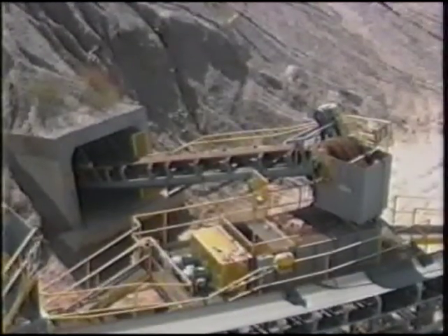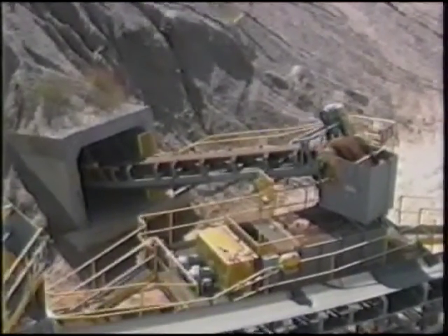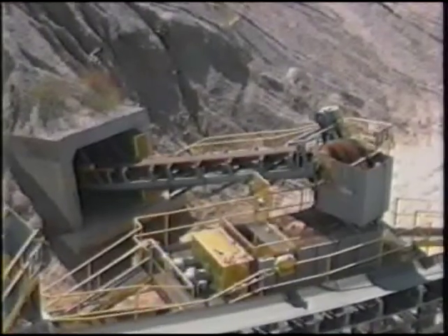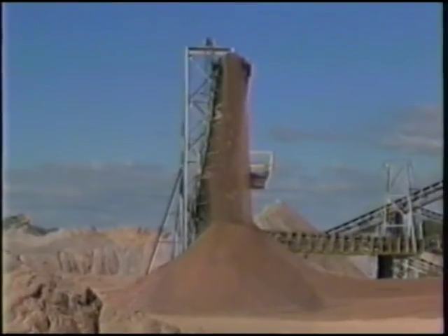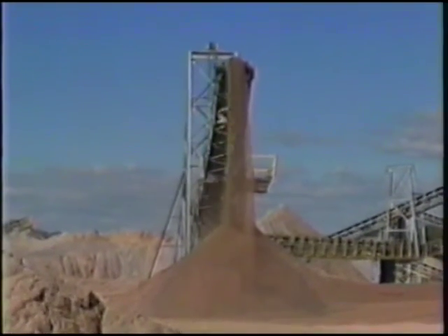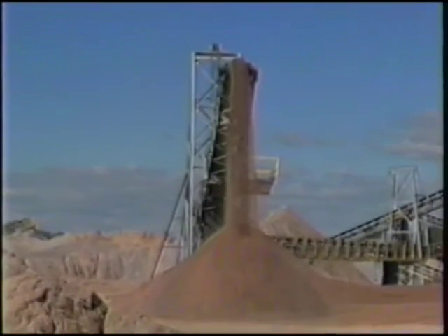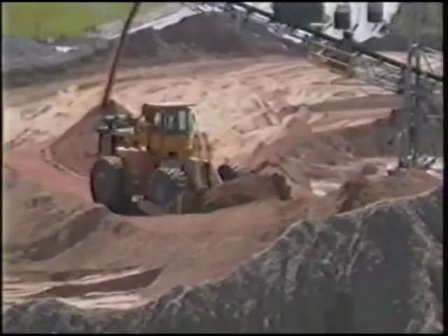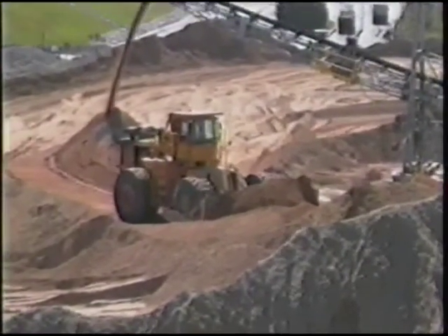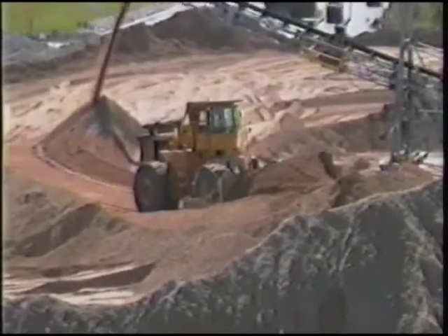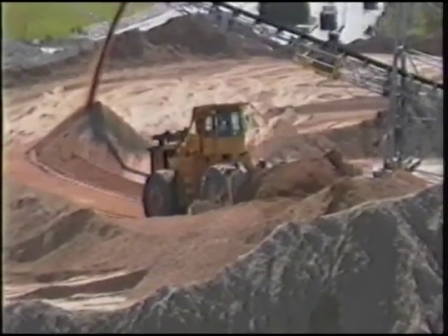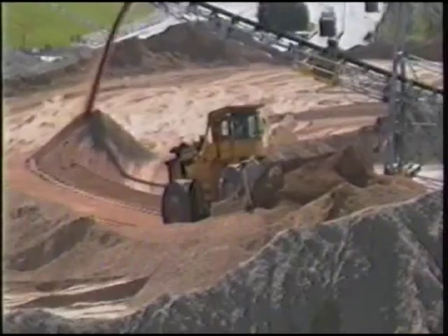Although pug milling blends the material, the same precautions must be used to prevent delivering a segregated, contaminated, or damaged aggregate to the pug mill. The drop from a conveyor could cause the material to segregate. Don't have the conveyor drop the material directly into the pug mill feeder. This dozer is pushing material into the feeder, mixing as it goes. Pushing and mixing the material assures that a more consistent product is fed into the pug mill.